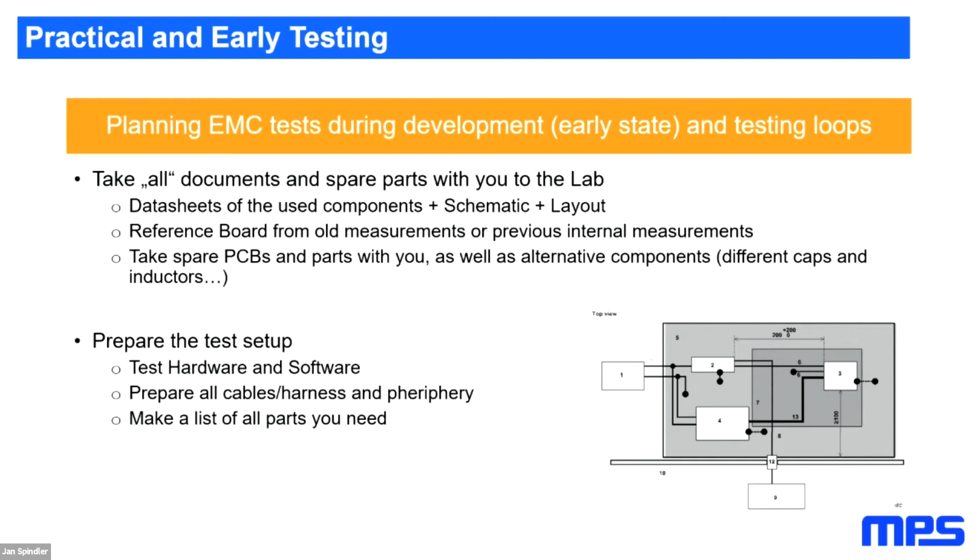An inductor is not an inductor. You have different vendors, and you see different constructions and quite often different performance, on the EMI as well. I'm not talking about the function and the DCR losses and so on. I'm talking about the EMI in this case.